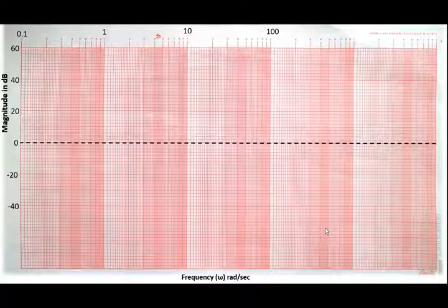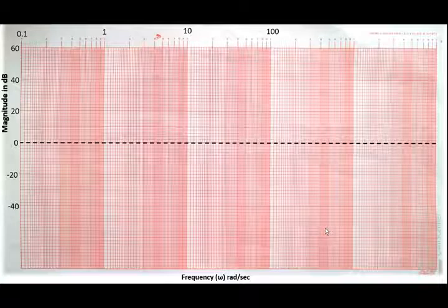And the next method is root locus. In the root locus, we knew that the total number of roots we obtained from the transfer function are present on which location and how they are moving, in which direction they are moving, whether they are finite or infinite, whether the system is stable or not. Not to make it stable, what we need to do, that we discussed there. That is the advantage over RH criterion, because in the RH criterion we were not knowing the total number of exact roots which are present on the right half of the S plane, to make the system unstable.